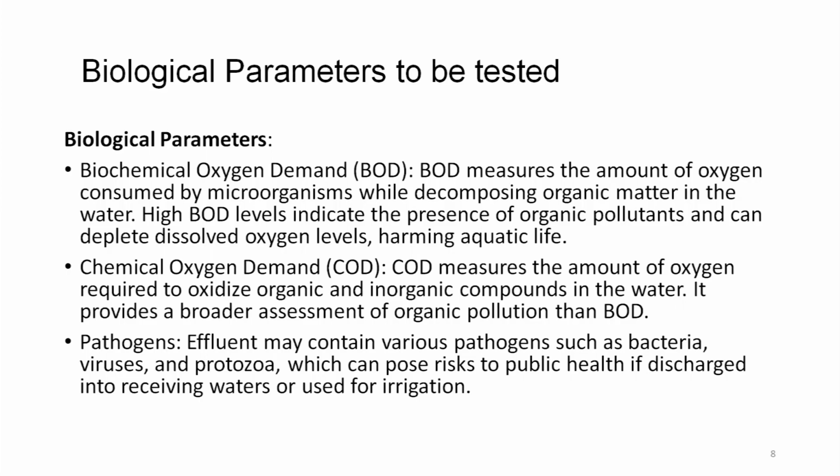Chemical oxygen demand, that is COD, measures the amount of oxygen required to oxidize organic and inorganic compounds in the water. It provides a broader assessment of organic pollution than BOD.